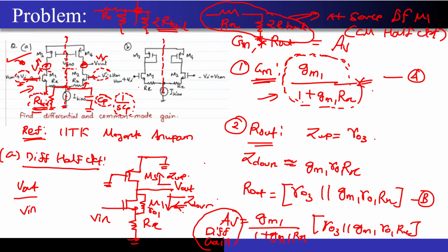We want this circuit to be perfectly symmetrical, so that any common mode excitation will face heavy rejection, correct. And to get that, we have to make sure that the transistors are matched as close as possible, correct. And what do we need to do to match them closely? We need to increase the area, correct. We need to increase the product of W and L.